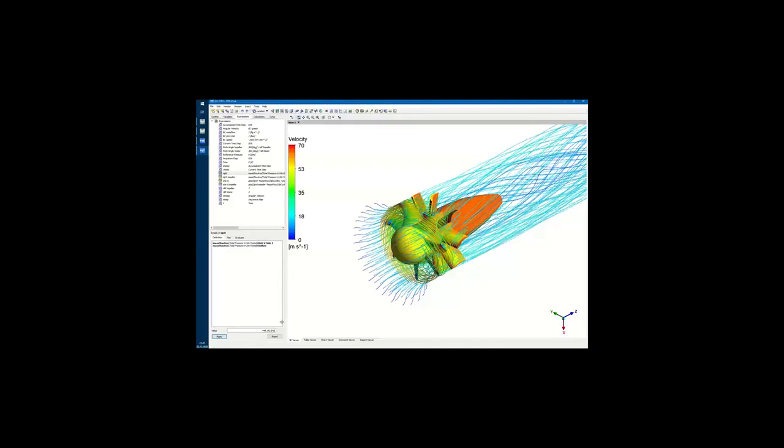In this case, we would need to specify new geometry iterations by making adjustments to our parameters. This can be done by going back into the project schematic, and I will show you how to easily create new design variations of your turbomachine. Therefore, I'm going to open the parameter set again. Inside the table on the left-hand side, you can see the parameter values of your current design.